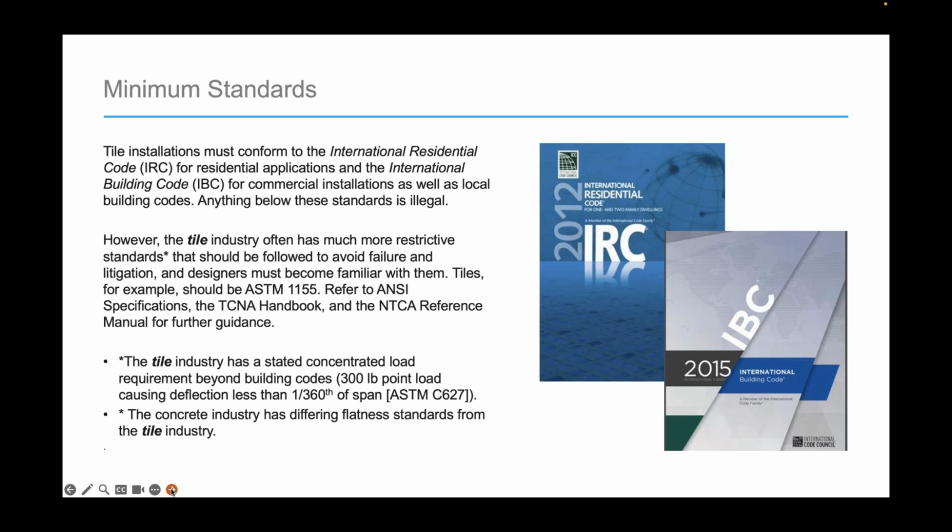The tile industry has stated concentrated load requirements beyond building codes: a 300-pound point load causing deflection less than 1/360th of a span. And of course, the concrete industry has differing flatness standards than the tile industry.